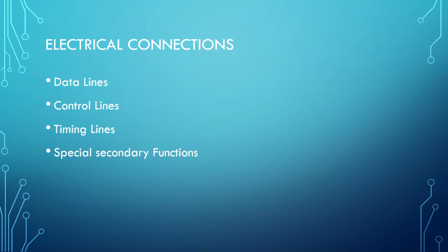So control lines are used for interactive device control, which is commonly known as hardware handshaking. And this regulates the way that data flows across the interface. Normally, if you have something to say, you might raise your hand, and I'll say, yes, go ahead. And you'll say your piece, and then we'll move on. That's the same idea going on here with the serial control lines. They're allowing the devices to say, hey, I have something to say, and the other says, all right, go ahead and send it, I'm ready to listen. Instead of always having to be ready to listen.